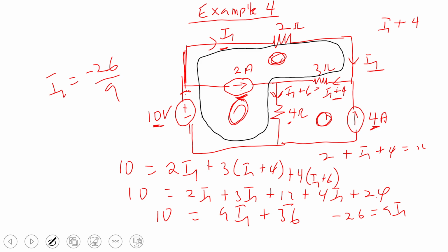Just assign your current direction anyhow. Follow the process: use the Kirchhoff current law to know the current in the corresponding branches. After that, use the Kirchhoff voltage law to take your loops, and make sure you don't take a loop with a current source, and you are done with Kirchhoff. Now, any question that has to do with Kirchhoff, you should be able to solve.